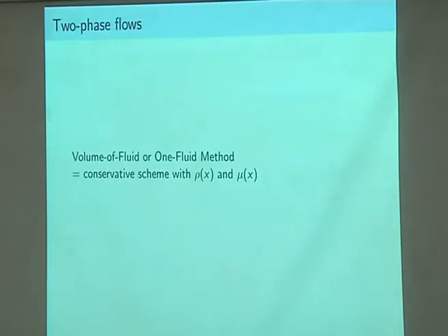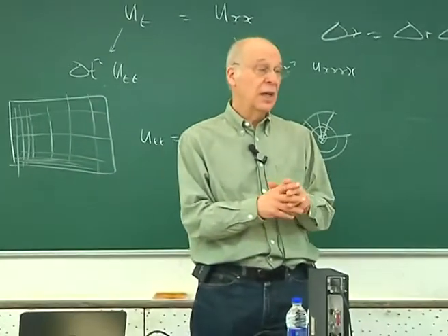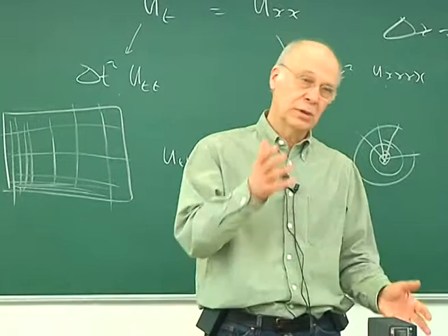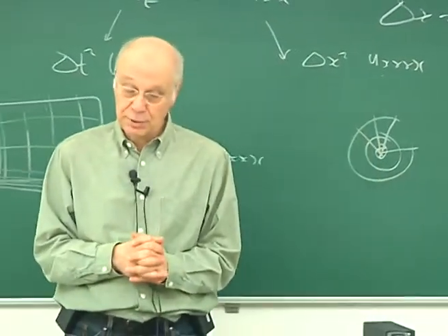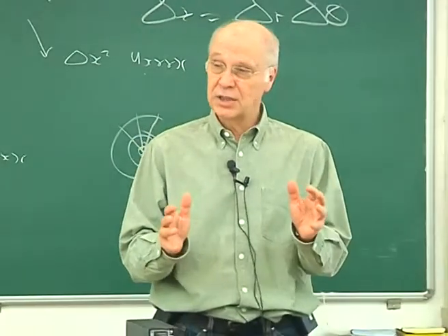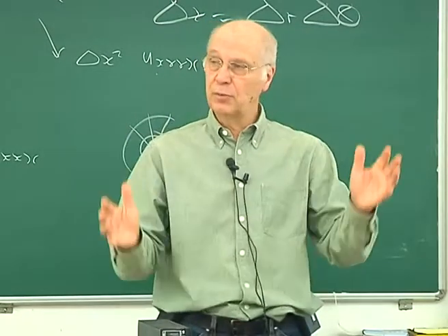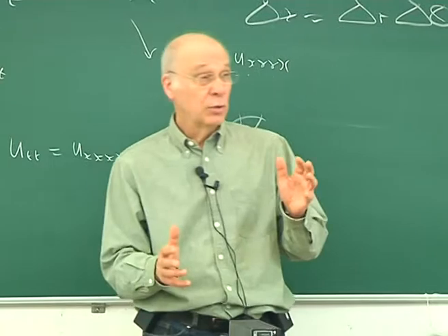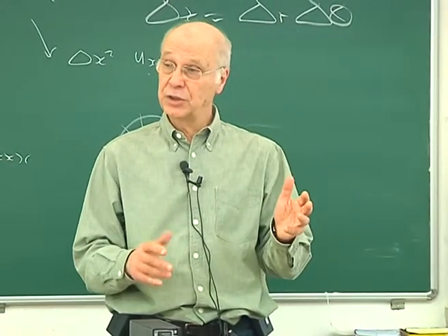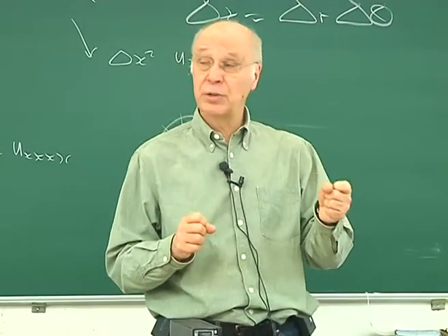Okay. So I've been interested in just the flow of a single liquid. I'm also quite interested in my research in two-phase flow, having air and water, or two different liquids. And there is an approach to computing that two-phase flow, which is to say, well, it's all one fluid. It's all fluid, isn't it? Let's call it one fluid. Use this volume of fluid approach, and you allow the density to be a function of position and the viscosity to be a function of position. The value is, what liquid are you in?